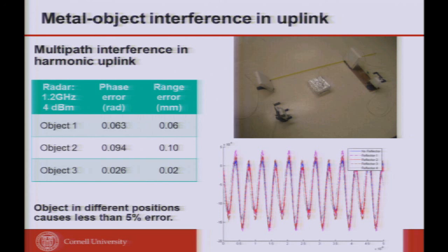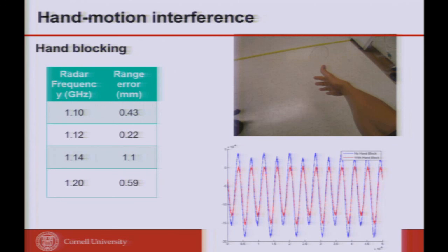The ranging error caused by the phase noise is smaller than what I can measure. This is something I tell the students: you cannot measure 0.06 with a tape measure. But this tells you that under these conditions, the phase noise doesn't dominate. You can wave your hand, you can walk around, and it is stable enough to give you sub-millimeter precision still.